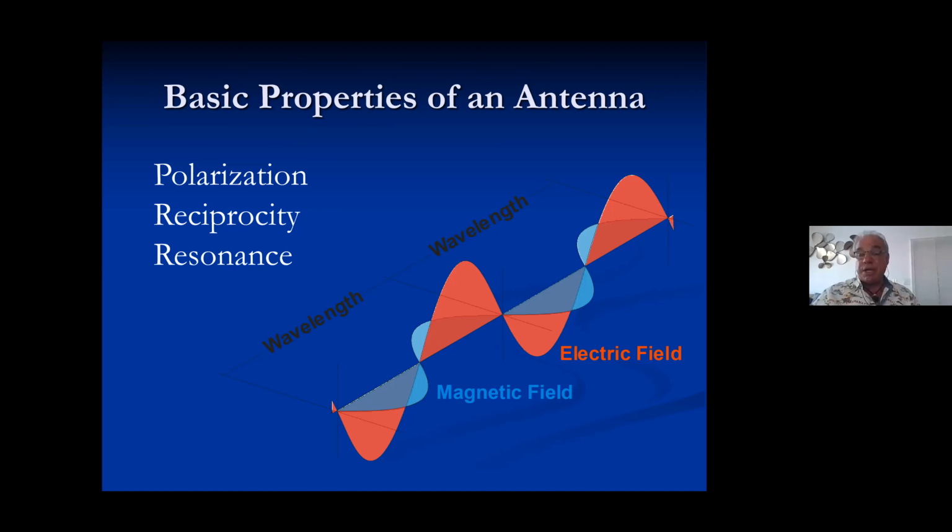But it comes into play, especially when you start to talk about wireless microphones, low power devices, and point-to-point links. If anybody uses like a Shure in-ear transmitter or PSM 1000 with a bunch of wireless mic receivers like UHFRs, you could put into the same sort of tone code squelch so that they speak the same language. Well, polarization becomes very important when you want the transmitter, which is stationary, and another receiver, which is stationary, to have maximum transfer of energy.